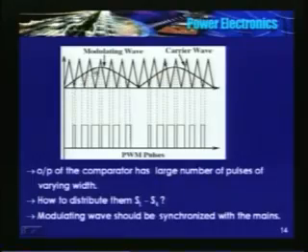See here, I have rectified a step down version of the supply voltage, which is known as the modulating wave. Amplitude is continuously changing, or the magnitude should be variable. Why? We will see later. The high frequency triangle has fixed magnitude as well as fixed frequency. Intersection will determine the switching instants.